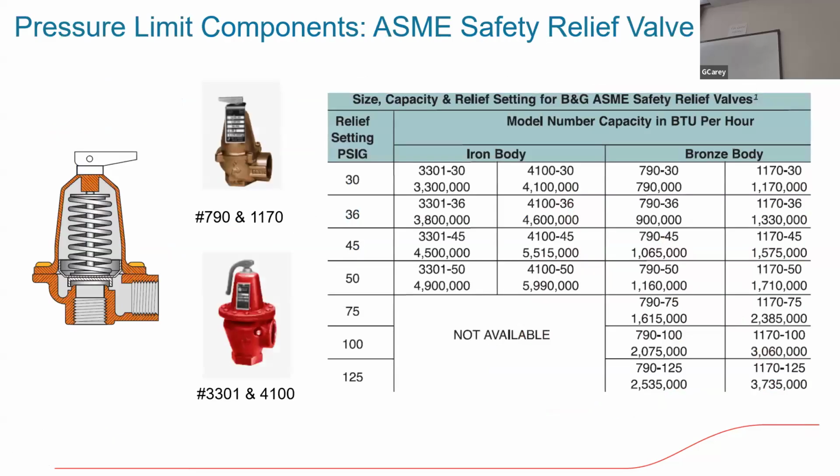Because if I don't and the pressure rises, what's going to happen? What are these guys going to do? They're going to open. What's the problem with a closed system having a relief valve open to get rid of that excess pressure? Bringing in more air. Why? Because you're going to refill it with cold water. And the cold water has what? Plenty of oxygen because it's cold. It's in solution. And then we put it through that heat source, boiler, heat exchanger, whatever, and it releases it. And you keep doing that, you can start to corrode your system, as well as the cost of water. You're bringing in makeup or you're dumping it.